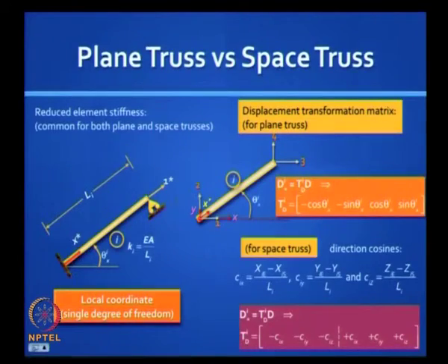Why is it minus for the first 3 and plus for the next 3? Because if you are looking at this corner, I have not drawn a picture, you have 1, 2, 3, you will find that you are pushing the element inwards. So the element is going to contract, whereas at the other end you are pulling the element outward, so it is going to elongate, right.